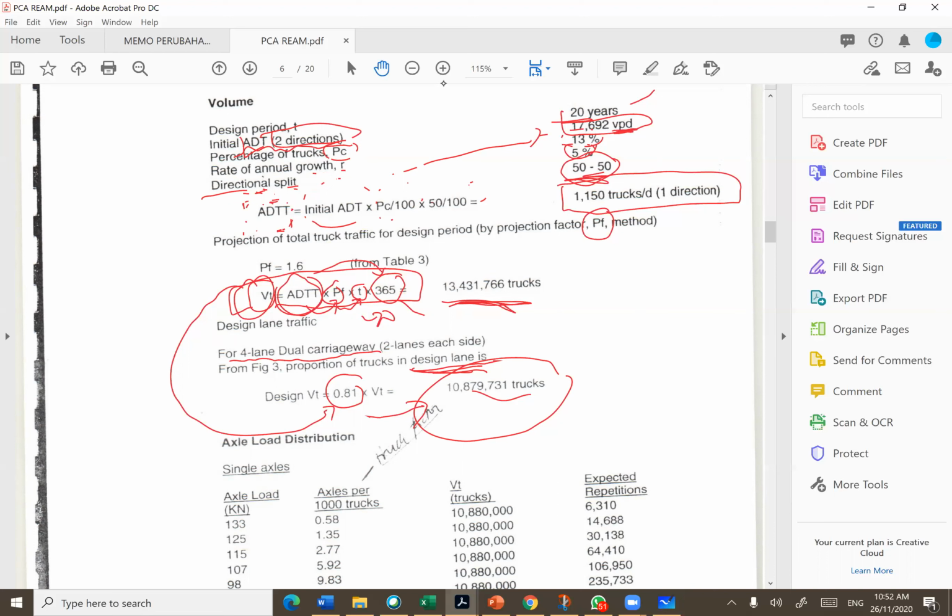Or let's say you have traffic study data saying that those going to Johor Bahru is 80% and those going to KL is only 20%, then you can use that. But you need to have exact traffic study information on that. Practically, though, they use 50-50 for directional distribution. Okay, Zaid. Thank you, Doctor. Okay, so done.